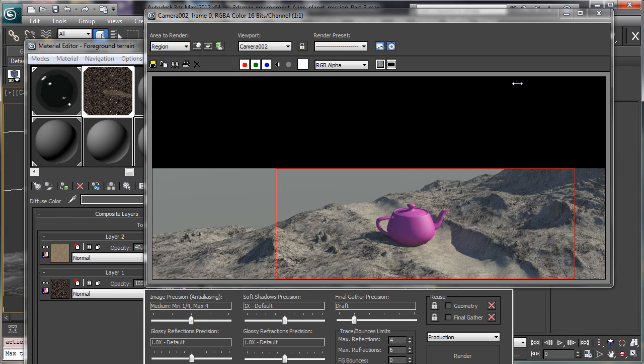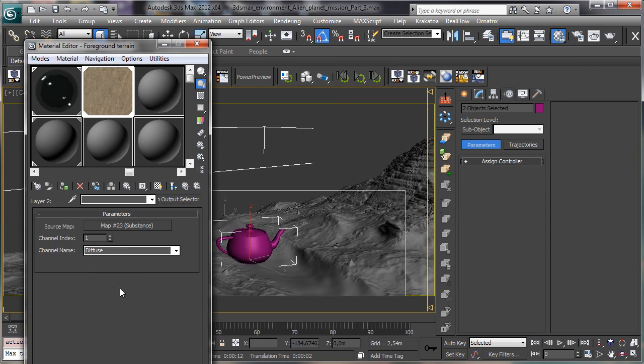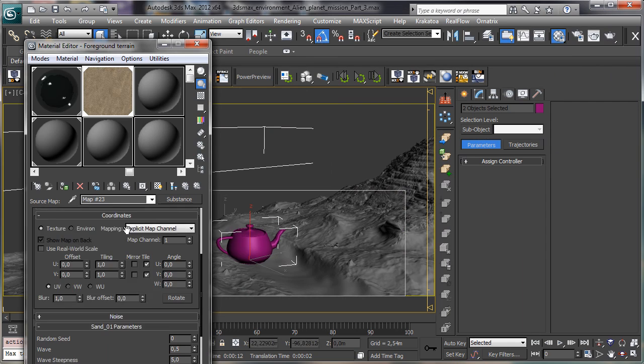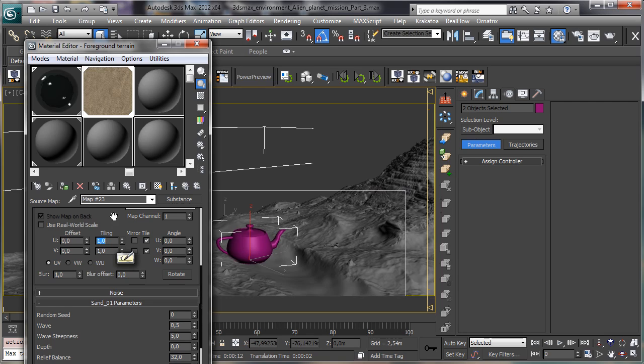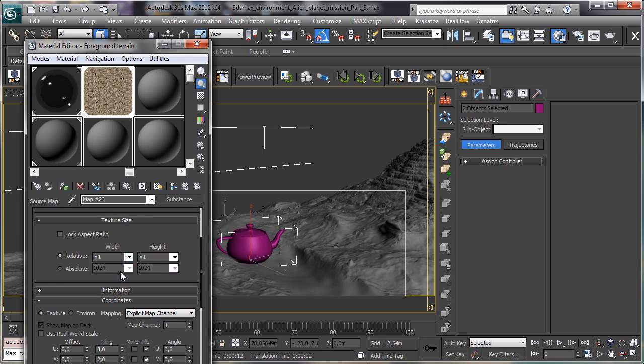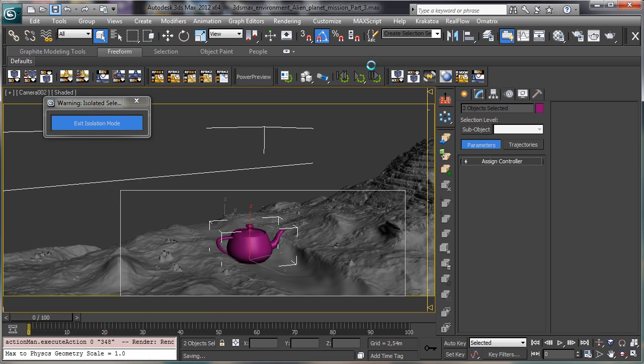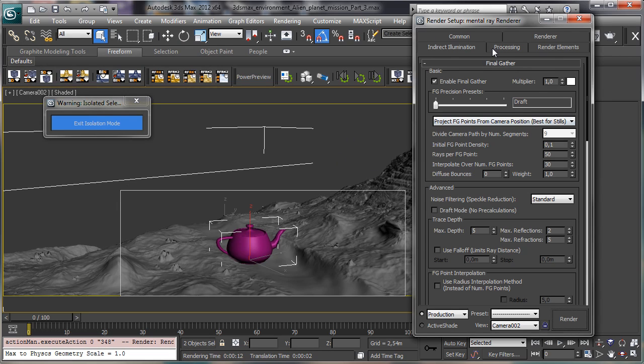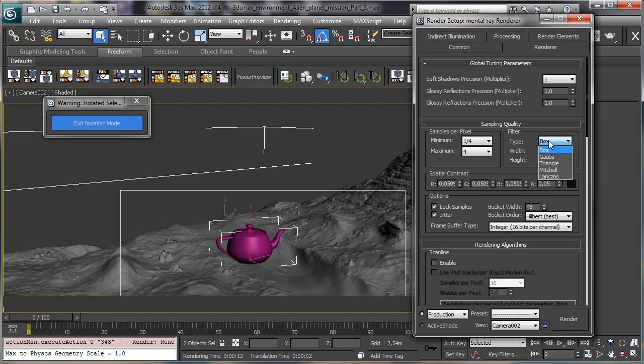Okay, perfect. And now I'd like to go there, and we have to choose obviously a good quality there. So let's try with the same, so 3 and 2, and we'd like to have no blurring, and let's go to choose the scaling, and we go for a 4K and 4K, and save. Let's try to make the same rendering with a good quality anti-alias for the moment to see how it is going.